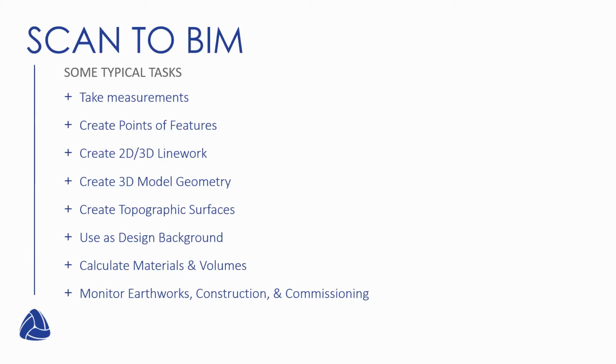So when seeing those then in section, you can, for example, create a cross-section of a road, or you can model a road by use of corridors. We can use it to create topographic surfaces. So you're not limited necessarily in that sense to roads itself, but you can use it, for example, to create a parking lot topography. You can use it to create stockpiles at mines and so forth.